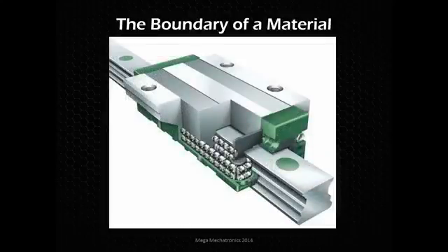And here you could see a little bit more complicated system of a linear bearing system. You see there's tiny ball bearings, and those are highly polished, probably plated with a very hard material, a very extremely good surface finish. You can see they almost look chrome, they're reflective, and those are riding on another very highly polished rail system.